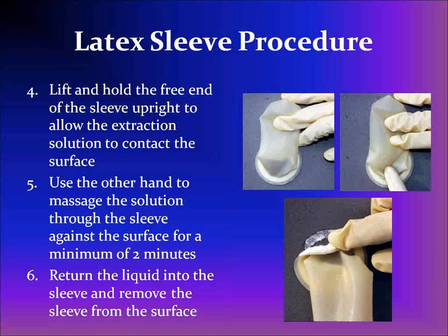With one hand, lift and hold the free end of the latex sleeve upright so that the extraction solution comes in contact with the test surface. Use your fingers on the other hand to massage the solution through this latex sleeve for at least 2 minutes. This helps to pull the contamination from the surface into the solution.